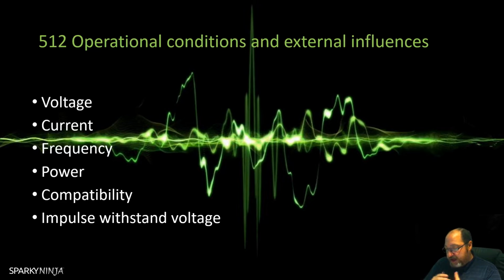The current, similarly, we must take account of the design current, considering any capacitive or inductive effects. A good example of that would be a motor with power factor correction. Okay, and the current likely to flow in abnormal conditions for such periods of time as are determined by the characteristics of the protective devices concerned.